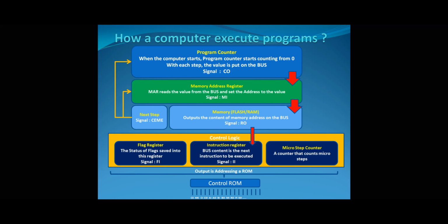And that's why normally in most computers, the first address is pointing to some sort of non-volatile memory, which could save some instructions in it, right? So in case of Bravo, we are pointing to flash, and basically we are addressing the memory. And once we address that memory, then obviously we're going to have some content in that memory address. And if you want to put that content on the bus, then we're going to use a signal called RAM out, right?